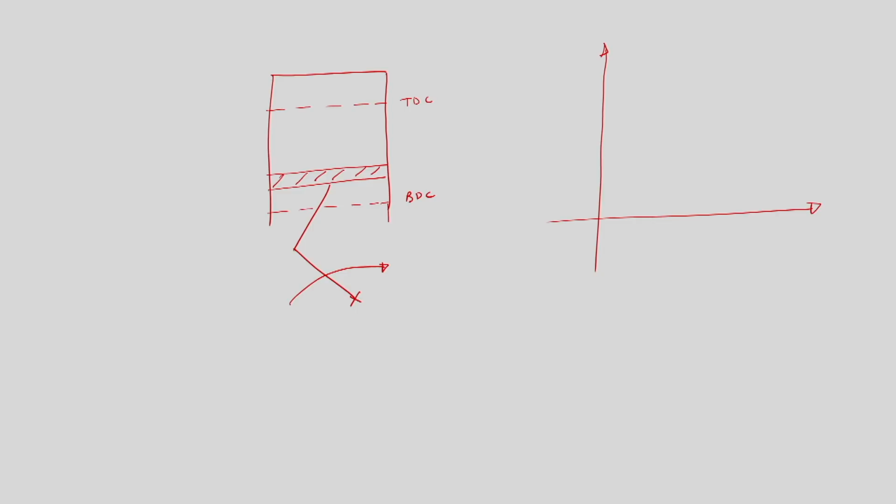Now whenever the piston is coming from TDC to BDC, as I have discussed, we are creating a vacuum inside the cylinder. Suppose this is the atmospheric pressure, PATM, and we have two different volumes, this is VTDC and this is VBDC, the volume of the cylinder. Whenever the piston is at BDC the volume will be this, and whenever the piston is coming to TDC the volume will be like this, so this is the swept volume, VS, and this is the clearance volume.